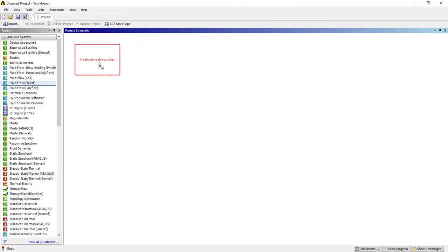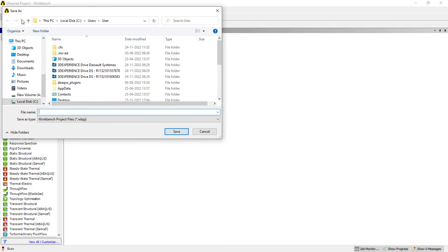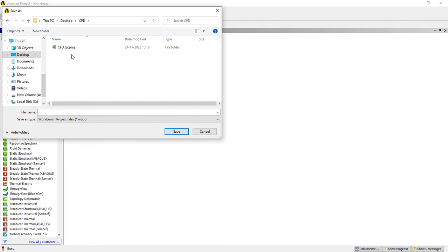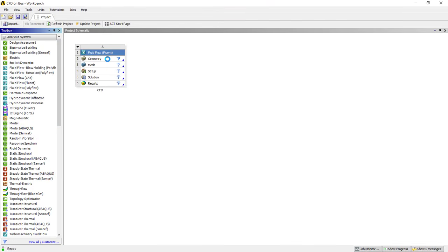So we'll start with ANSYS Fluent. You can just drag it and name it like this. For safety, I'll save the file directly, because while dealing with the analysis it crashed multiple times. Every now and then it's better to save the file or save a copy to protect your data. So I'll browse the file. I'm going to use only bus. I need to conduct this series of analyses: only bus, with camera, and with mirror.